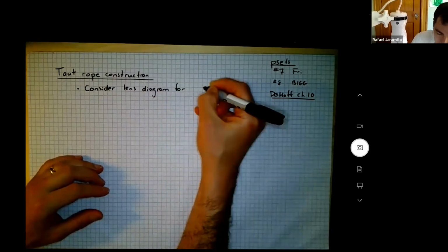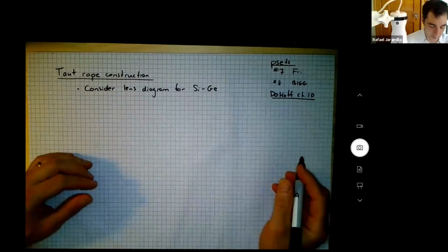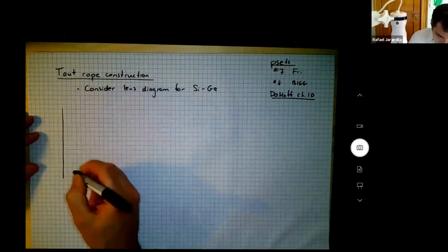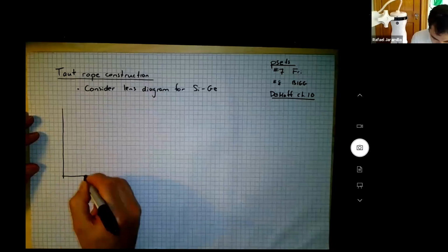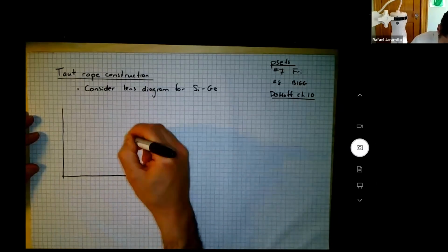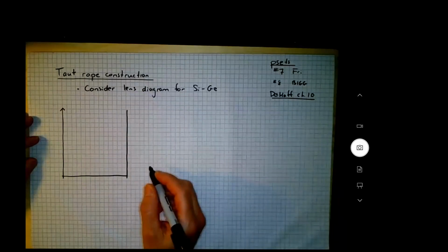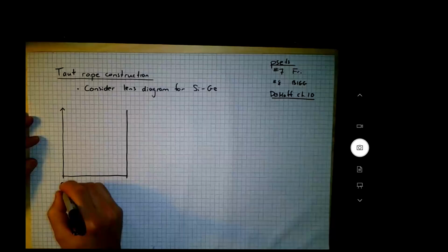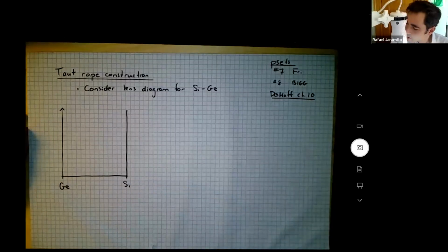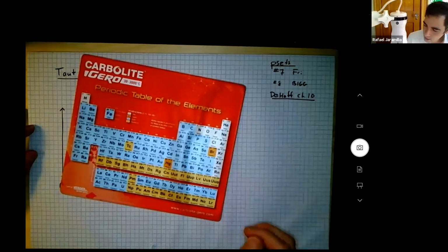That is the silicon-germanium system. So I'm going to start by drawing the phase diagram of the silicon-germanium system. Who has a higher melting point, silicon or germanium? Silicon. Silicon, a higher melting point, right? It's more strongly covalently bonded because it's a smaller atom and it's higher up on the periodic table in that column. So it has a higher melting point.